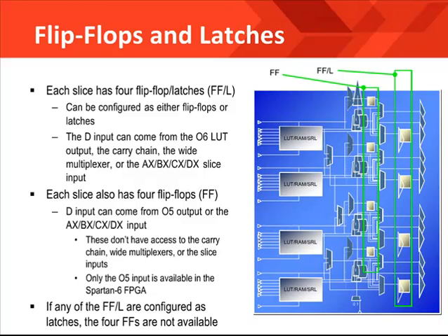Now, these limitations are not much of a big deal. In the end, if you're building lots of lower input functions that share inputs, which is required if you're going to have the 6-input LUT broken into 2 5-input LUTs, you should end up with the flip-flops being used quite a bit. Otherwise, these extra flip-flops will probably be used for pipeline delay elements.